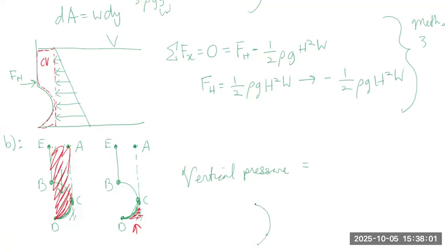Basically, this cylinder looks something like this, and it contains some volume of water, and it has a radius R and a width of W. So already we know that the volume is equal to the area of this semicircle times the depth, which is W, which is equal to pi R squared over 2.